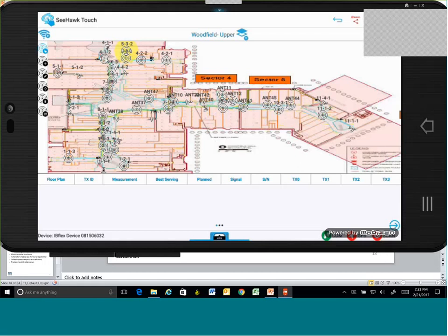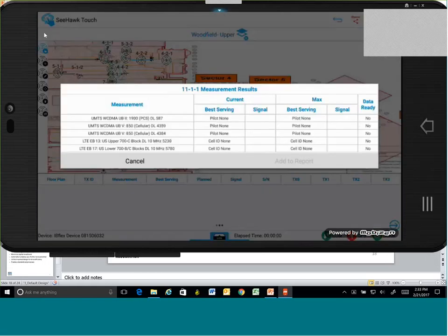All right, so now when it comes to the actual performance of the ABT test, like I said, it's relatively straightforward. You click on one antenna, turns it yellow, and you hit the test execute icon. And what you'll notice happens is we actually bring up this pop-up box. There was an interesting thing about working with the guys who did this. You'll notice that those middle columns give you real-time values. So if you were moving around a little bit under the antenna, they'd be going up and down.